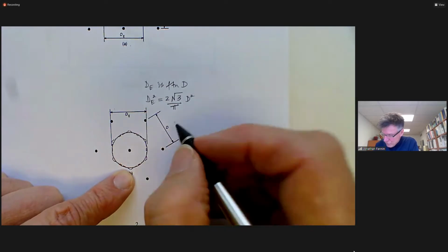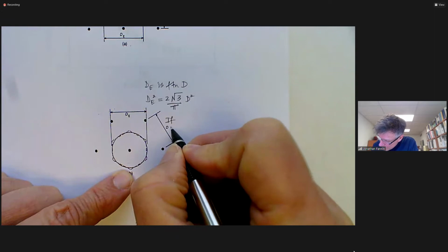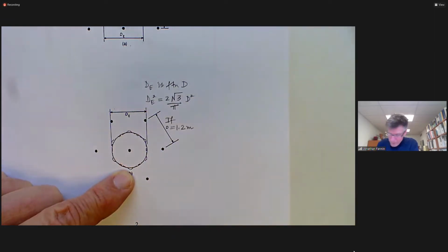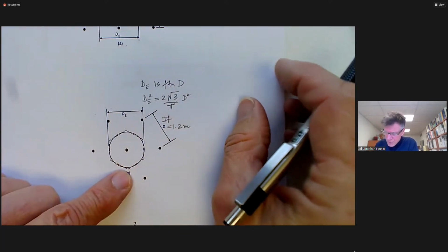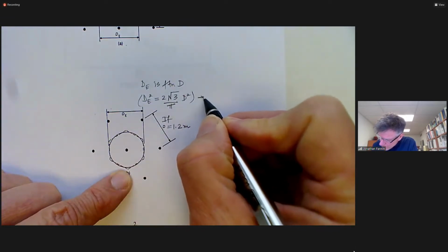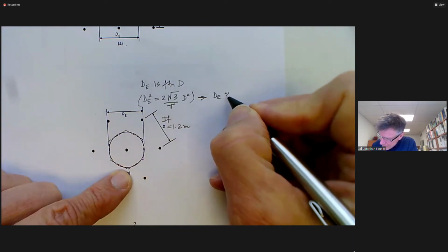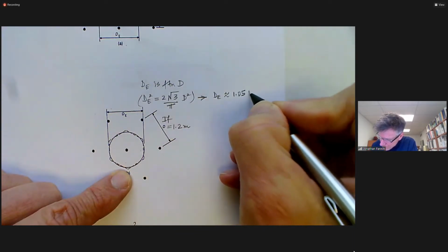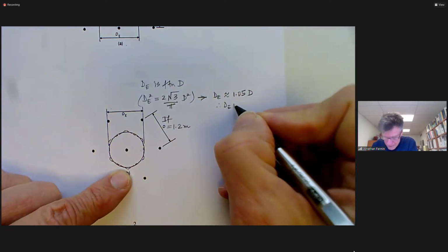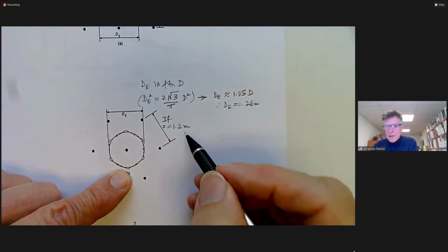And if that holds true, then for example, if we were to put them in the ground at a spacing of about 1.2 meters, and I think I'd choose that because that number is going to be relevant to one of the studies we'll look at. If that's the case, it doesn't make a huge difference. This results in DE being approximately 5% larger. Therefore, DE about 1.26 meters. So it doesn't make a big difference.